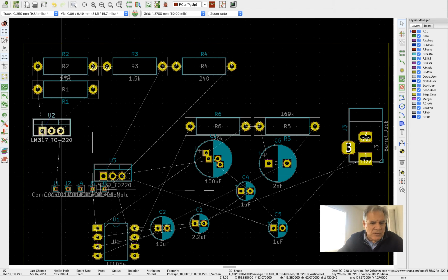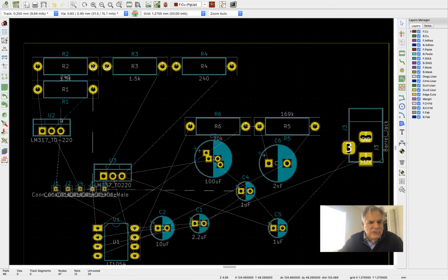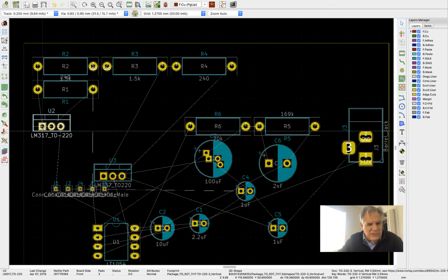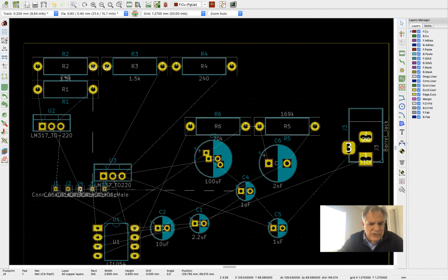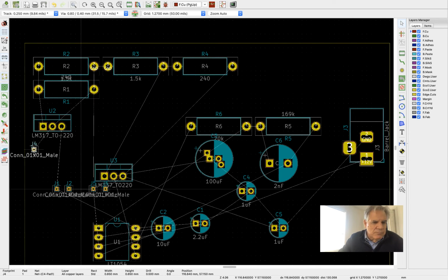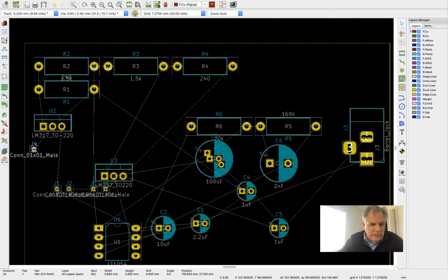Now this particular part here is a TO220, which you can look up, but this back is something that would like to be mounted to a heat sink in case you pulled enough. I don't think you'll pull enough power that you'll need it, but if you even want a small heat sink, you might want to leave a little distance on this back side of this transistor so you can put one in. It's an integrated circuit, but it's in the form of a power transistor. And some of this stuff maybe would like to be near the edge of the board and that kind of thing.